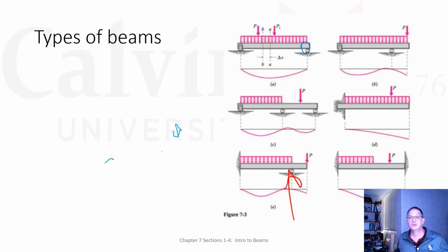I've got two vertical forces, one here, and a moment. And that means I've got 3 unknowns. I can't solve for all that. I have to take into account the strains. I like the statically indeterminate problems for beams. They're a lot more fun than the other ones.